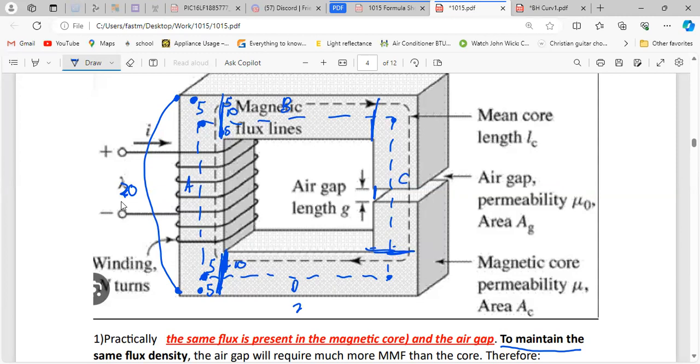So you have to subtract what you don't need. The piece that I don't need, I'll put in red, is this piece here and this piece here. This piece here is 5, this piece here is 5. So the actual length of the core part of this piece of the material, which is A, would just be 20, subtract the 5 from the top and the 5 from the bottom. So you actually get 10 for this here. Since the material is uniform, B will be 10. C now will not be 10, because C has the air gap in it. So C will be 10, which is basically from here to here.